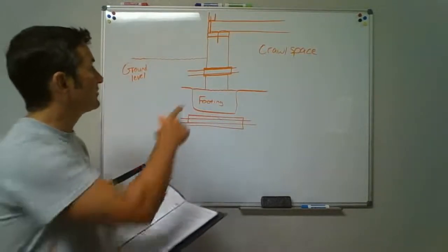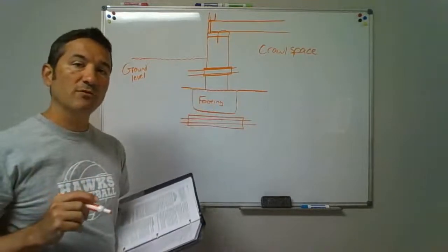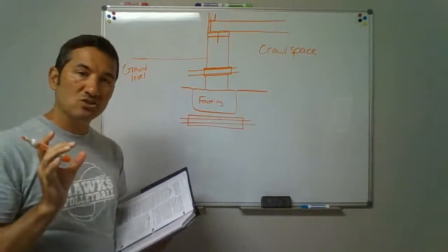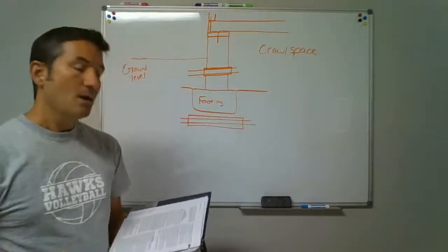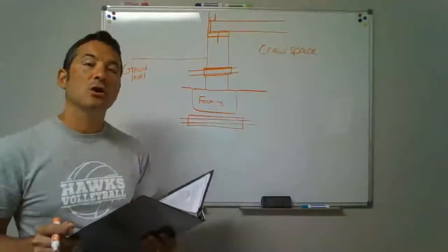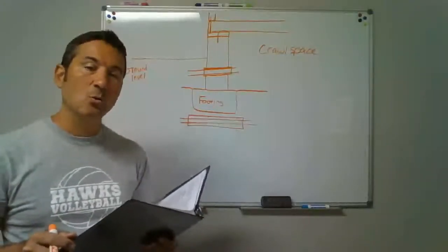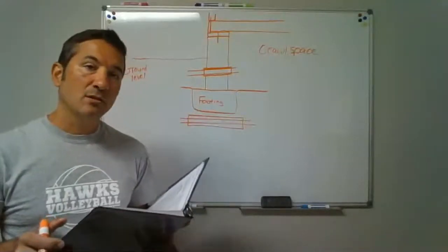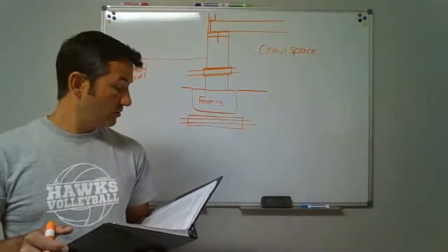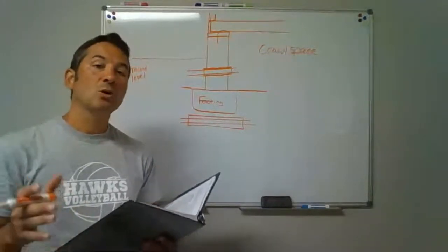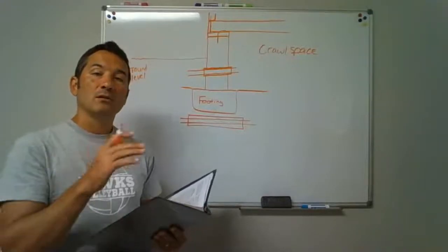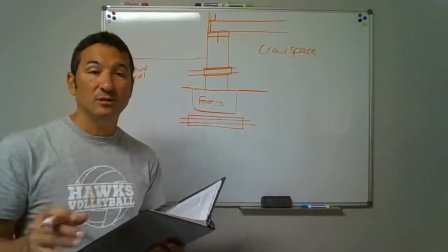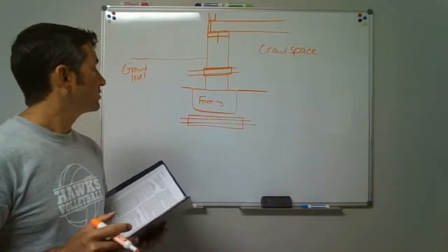It says that sleeve, if it's in here, it needs to be built into the wall. If a hole was knocked, it needs to be concreted back around to where that pipe is solid in the wall. Now, we're not concerned about the concrete going up against the sleeve. We're not worried about the corrosion that might happen, where that would become brittle. The sleeving is protecting the actual pipe. So even though it says on 305.1 that we can't have concrete up against pipe, well, it's not up against our pipe. It's up against the sleeving pipe. So that's fine. Okay, so we have it sleeved in.